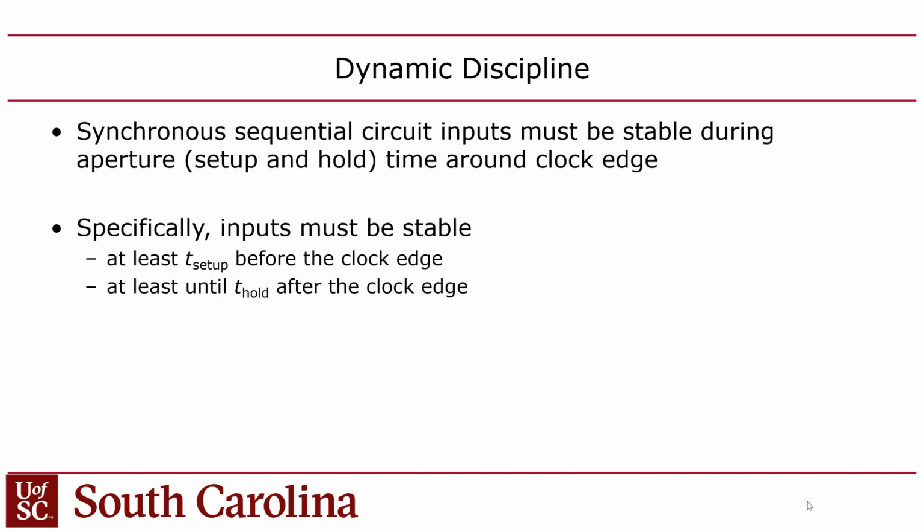As long as you adjust the clock rate such that you don't violate the setup and hold time after you calculate all your propagation and contamination delays, then things like glitches aren't going to affect you, and you can reasonably guarantee the user that the circuit will work. Make sense? So this is another part of what's going on when you compile your design.